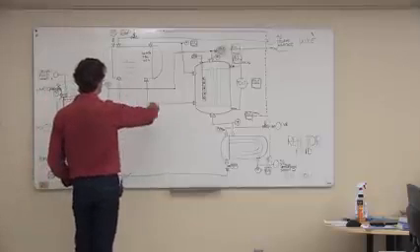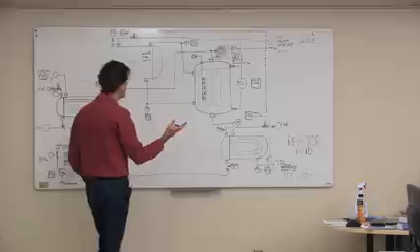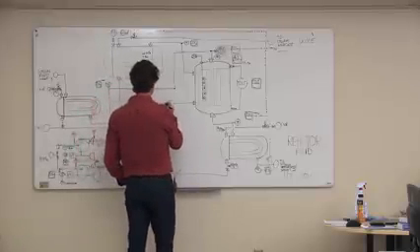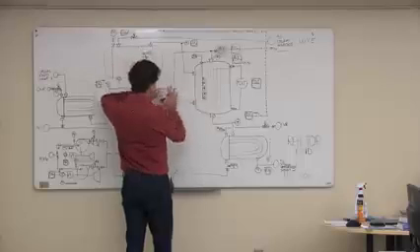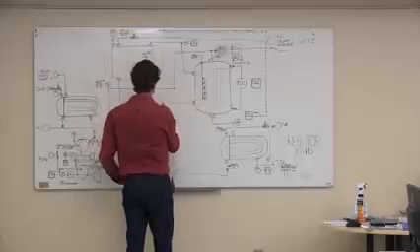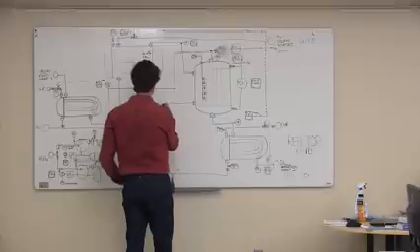Okay, so that's the water circulating around. We might be interested in knowing what the flow rate is. So if you've got enough differential pressure here, you could put a flow meter in. You could maybe try and find a very low pressure drop flow meter.